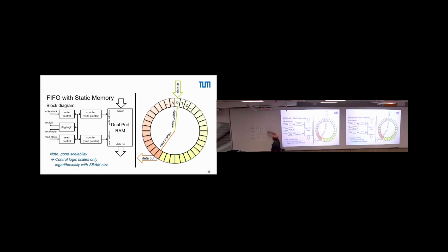These lines here should visualize where the first clock edges are. So this is our write clock. This is our read clock. Synchronous or asynchronous? Synchronous. This one here is a read clock. This is still the write clock. Asynchronous because it has a different frequency. This one here is the read clock. This is still the write clock. Asynchronous, we have a different frequency and different phase. Different phase alone would be sufficient.